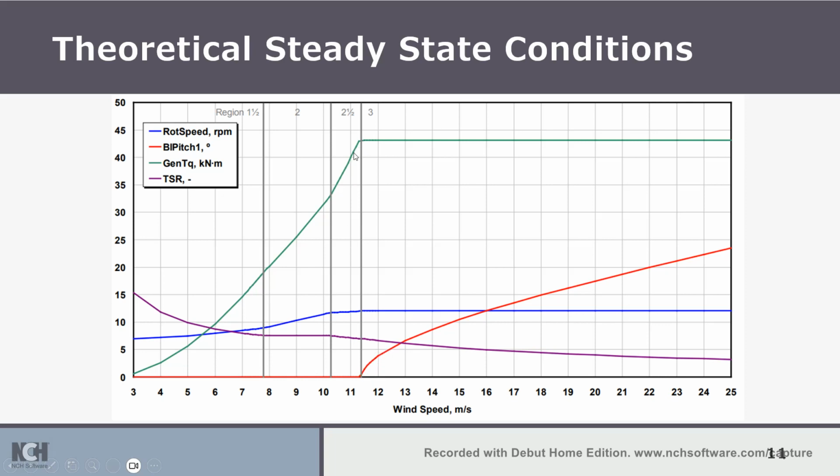And you'll notice these are the transient responses. It's still trying to get that torque generation up. And then it starts leveling out right here. So let's look at like 18 meters per second wind. We'll have a 15-degree pitch angle, but a constant torque. So it means our power generation is constant and most likely max power generation.